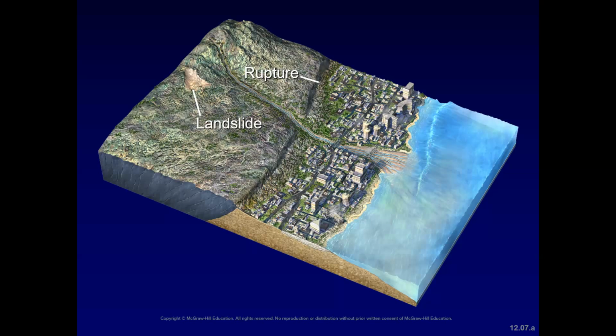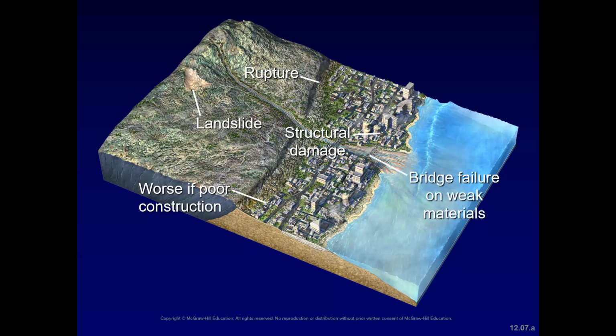Mountainous regions can experience landslides, rock falls, and other earth movements. And then we'd anticipate structural damage as well. That depends on the type of construction. If you have a lot of concrete and masonry, those are rigid, so they're more susceptible to damage. Of course, it's going to be worse if we have something that's considered to be poor construction. I'm not an expert in that, but if you don't have a structure that can stand up to movement through it, of course it's going to fail.